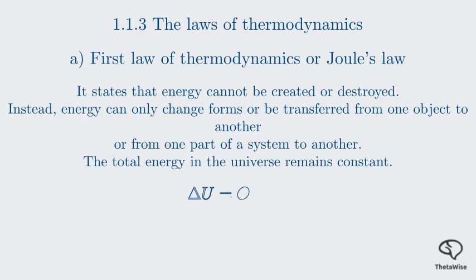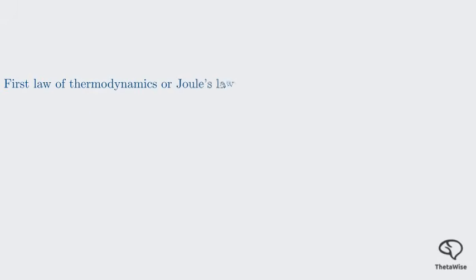The change in the internal energy of a system, dU, equals the net heat transfer into the system, Q, minus the net work done by the system, W. The equation dU equals Q minus W is simple, but its application depends crucially on the sign convention. Let's break this down. This table from your notes is essential for getting the signs right.